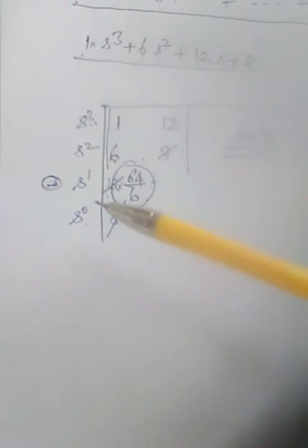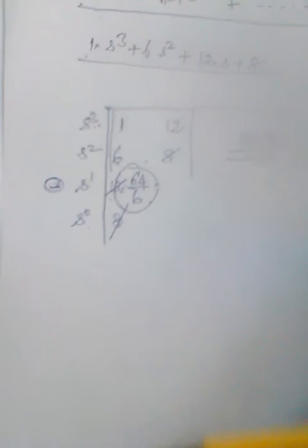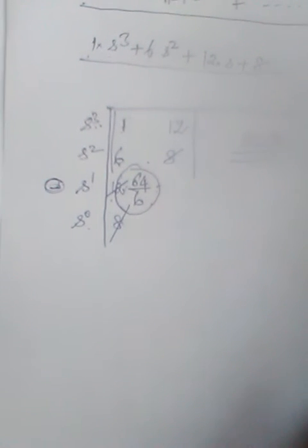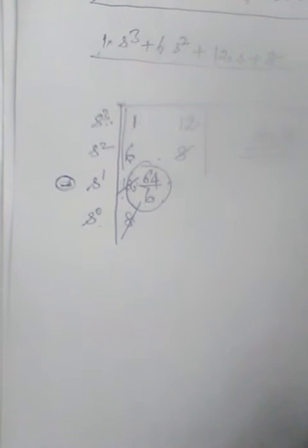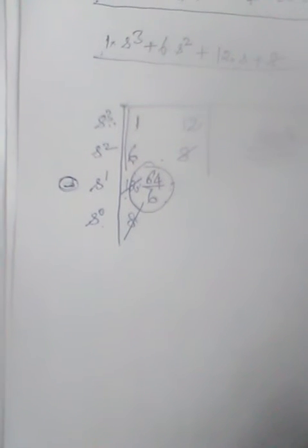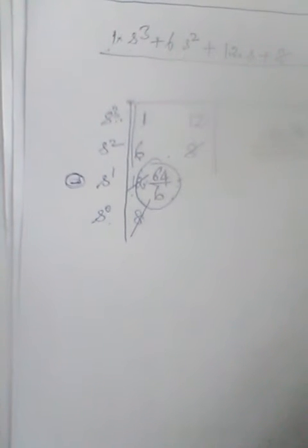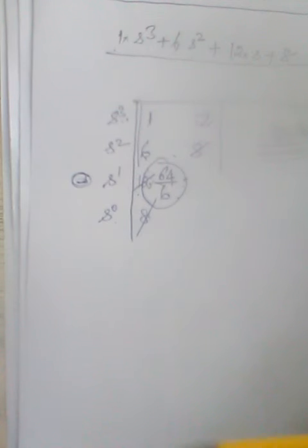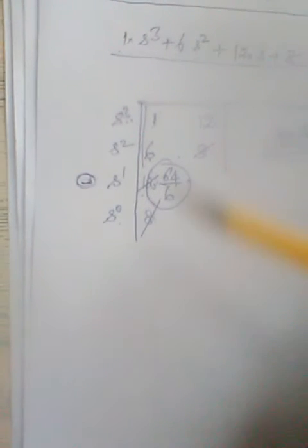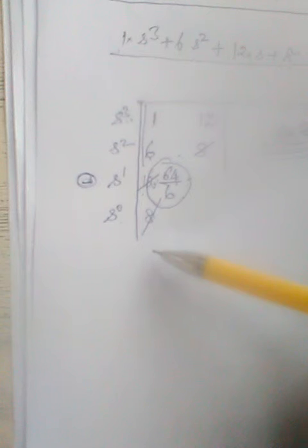Then if there is a change of sign in the first column of the Routh table for the system, it is going to indicate that it will have some real part which is going to be negative or positive, depending upon the multiple changes in the sign in the first column of the table. This is the first column of the Routh table constructed.